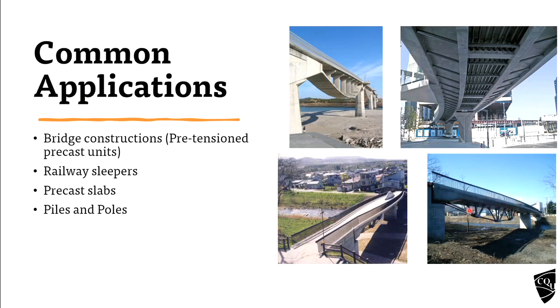Okay, so I will explain this pre-stressing technique in a minute, but pre-stressing wires are outside the section, something like this, but it is well outside, and you can see it actually goes up here. It goes up. This is also a pre-stressing tendon. Goes up and goes down again. So this is a two-span pedestrian bridge.